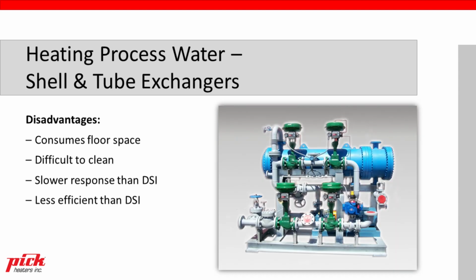Some of the disadvantages associated with shell and tube heat exchangers are they do consume a lot of floor space. As I mentioned earlier, if you do run on lower pressure steam, that 15, 30, even lower pressure steam, you need to add surface area to that shell and tube heat exchanger to get the same heat transfer rate. So everything gets much larger. The diameter gets bigger and the length gets bigger. So that's where you take up a lot of floor space. And they can be difficult to clean. If you have to take that tube bundle out, you have to have room on the exterior side of where the bundle is to remove that tube bundle.